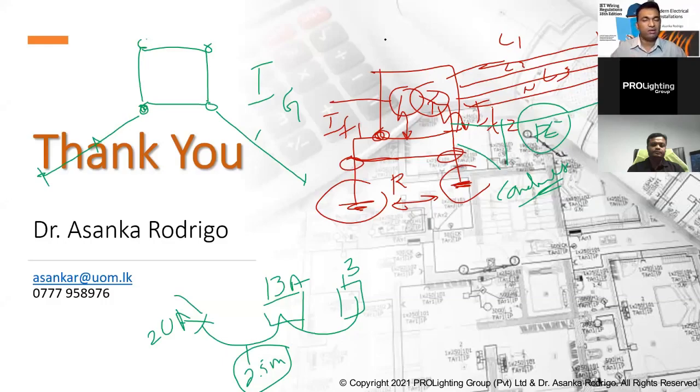So in that special kind of installation, rather than having earth fault protection, you can have the separated system. Some of them are functional requirements. If you have a functional requirement, then anyway you have to run the earth conductor, but that will work as a separate system with the IT. Thank you, sir. Without an isolation transformer, can we go like that? It's just with the isolation transformers only.